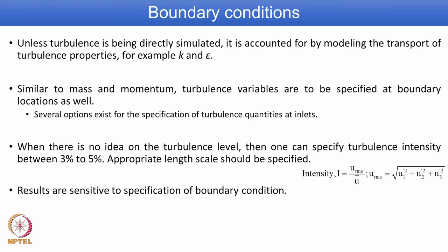The interpretation of the variables is that each one of them represents an instantaneous quantity. If you use the instantaneous Navier-Stokes and continuity equations as they are, then you are actually doing direct numerical simulation. You have only 3 or 4 variables, 3 velocity components and 1 pressure. We prescribe boundary conditions for them, and there is no need for knowing boundary conditions for k and epsilon.